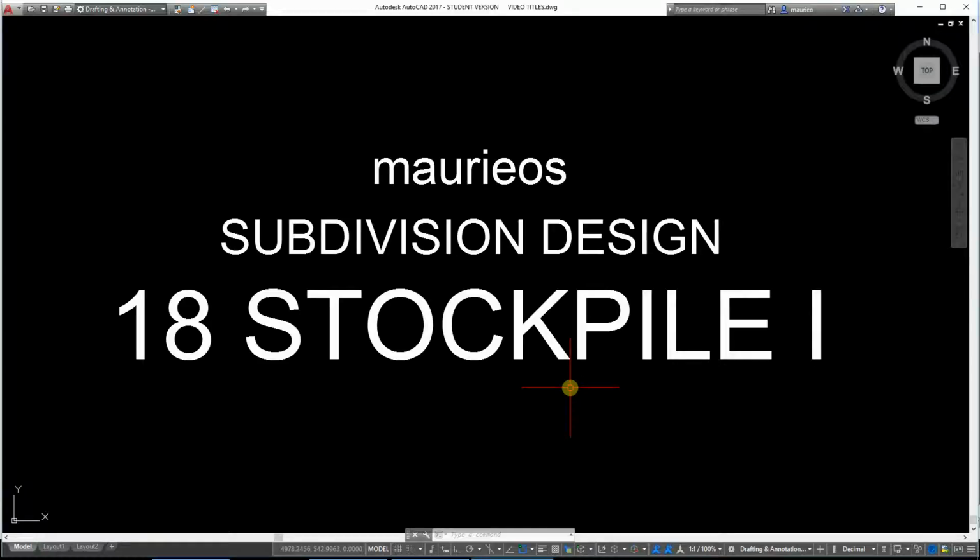In this video I'm going to take a look at creating a 1500 cubic meter stockpile on the existing surface that I did last time. I've done a few Fermi mathematical calculations and I reckon that my stockpile needs to be around 40 meters long at the top, 6 meters wide, about 4 meters high. That's going to give me roughly 1500 cubes. I'm going to have one-to-one batters on the side of it.